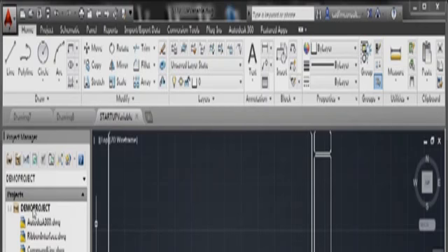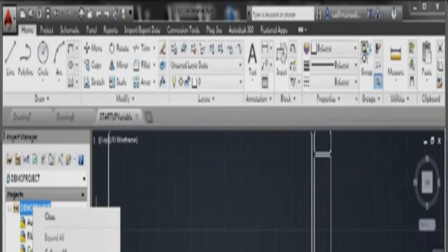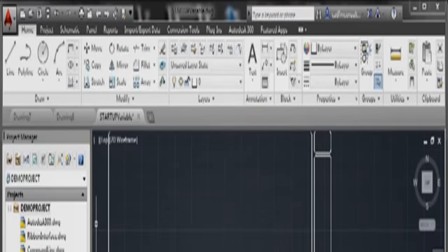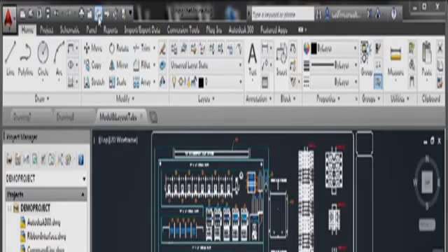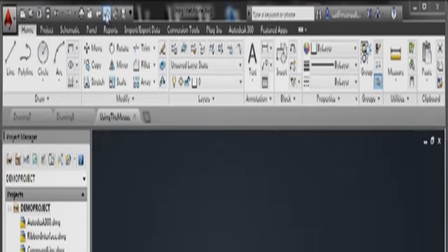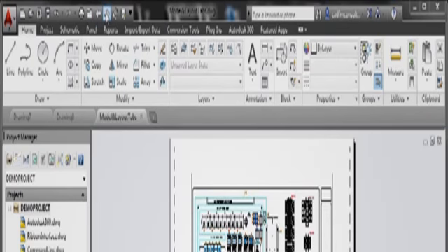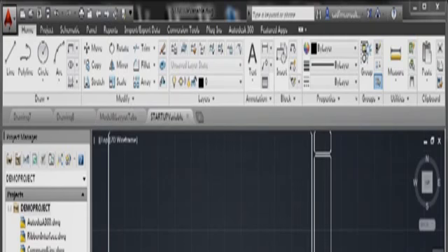And then we'll go to Demo Project, right-click, Add Active Drawing, and apply the project default values like so. It takes a few seconds, and there it is. The nice thing is now it's in the project, I can use these arrows here to toggle between drawings in the project. So that's my model and layout tabs. If I go back to using the mouse now, you'll see they update as I go through. I can go back now, just by clicking on the arrows, and toggle between the drawings in the project, which is a really nice way of moving around.